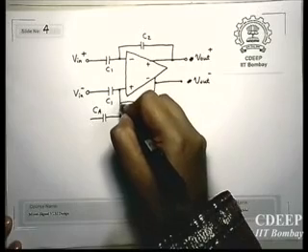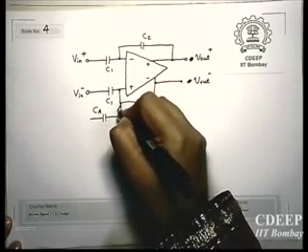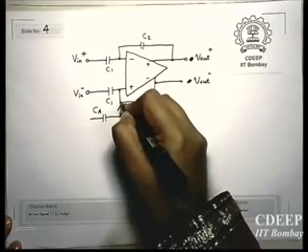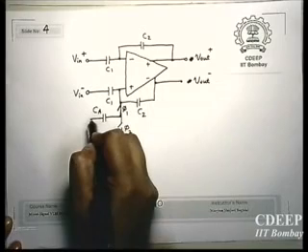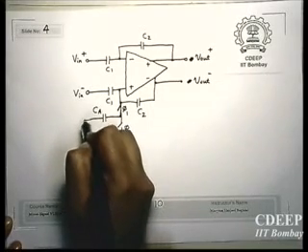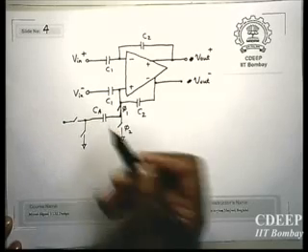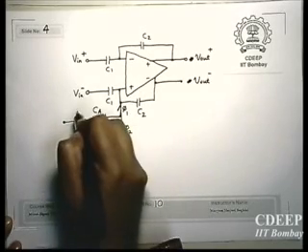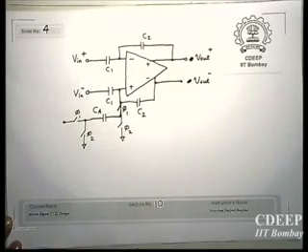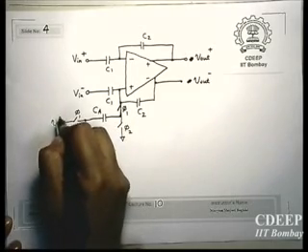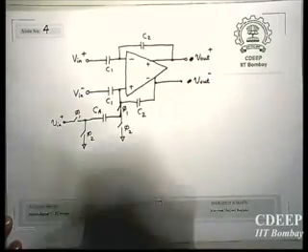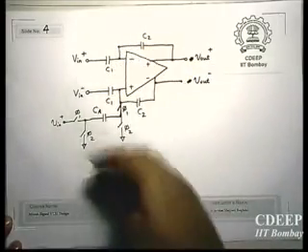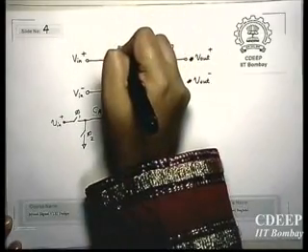There is a phi 1 here. Right. And then again here we have two switches, phi 2, phi 1. Because CA was negative, here I will use Vin plus. And then correspondingly the same architecture will repeat over here.